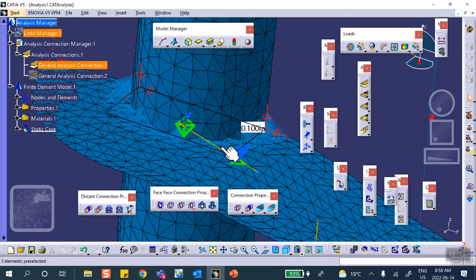And because I made surface to surface, remember I made surface to surface, fasten? If somebody does edge to surface, it's going to look different. Because here, I don't know internally how they wrote the code, these internal elements for me, even though it may be exactly the same mesh, we have done exactly the same thing, the difference is in that connection, edge to surface or surface to surface. The shape of those things will look different.